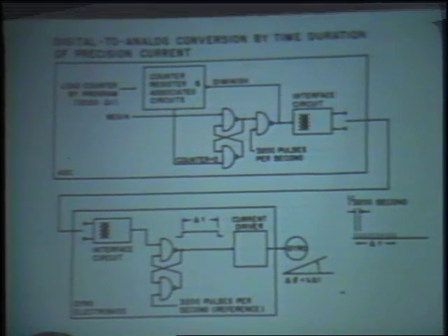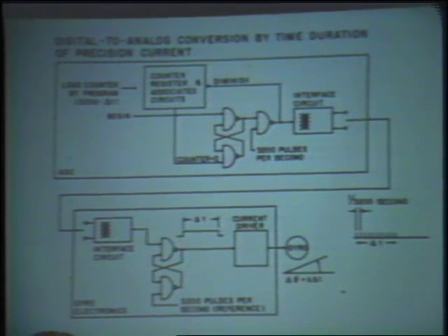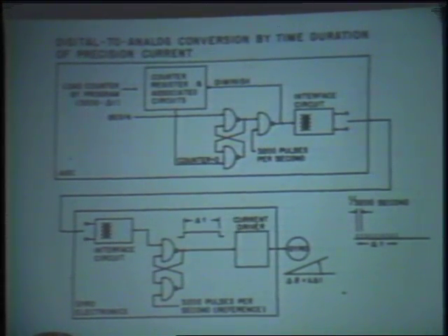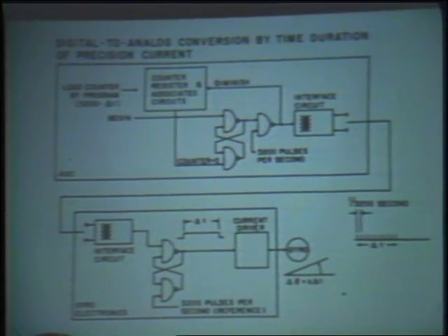So you send out a number of pulses, n, and it comes out here and sets this flip-flop, which generates that pulse length right there. And then the current drive electronics controls the amplitude, so the integral of this area determines the angle which the gyro turns.